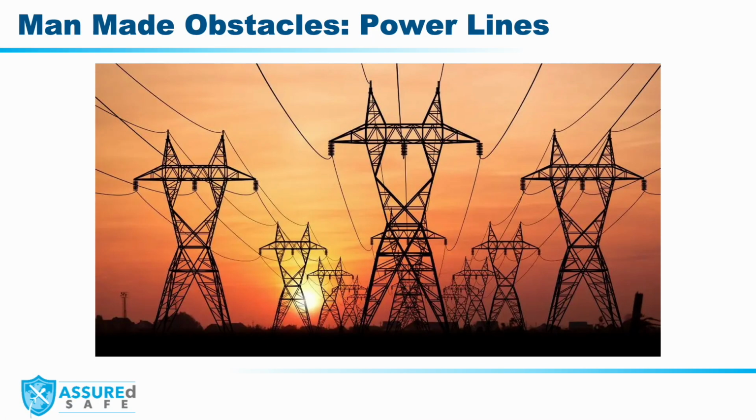Power lines introduce the possibility of exposure to electromagnetic interference for drones when flying in close proximity. This makes it important to understand the connection between the controller and the aircraft, and the fail-safe mechanisms that may take over in the event of a lost link scenario. Will the aircraft hover and wait to regain connection, or perhaps execute a return to base function? Similar to the guy wires of towers, power lines can be difficult to judge when piloting, especially at the extent of visual range.